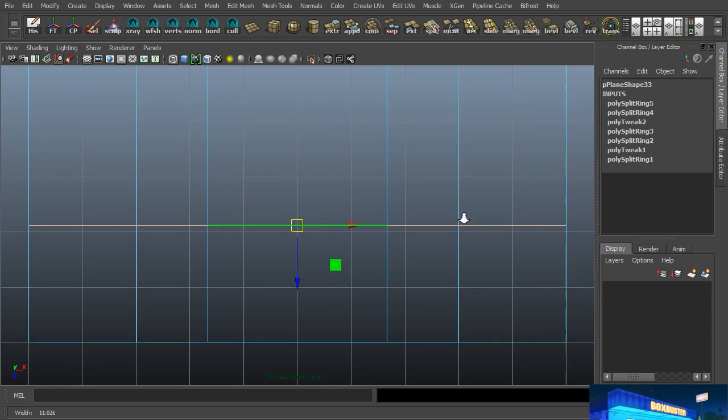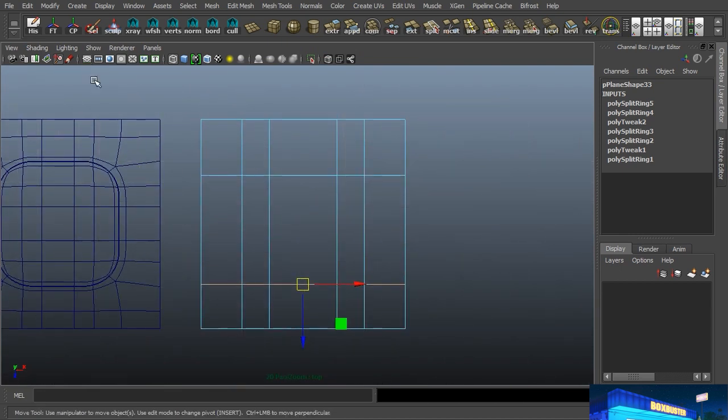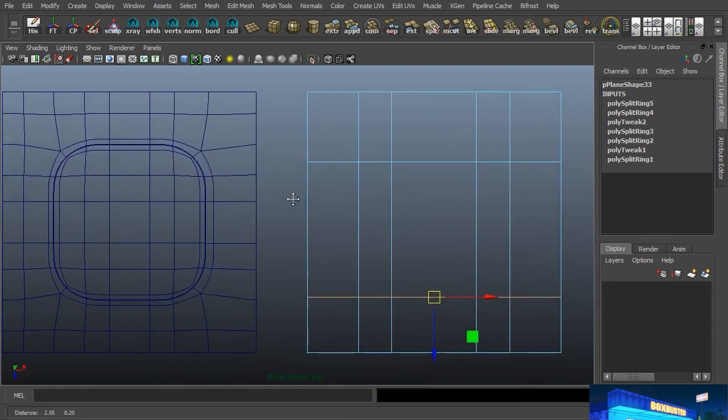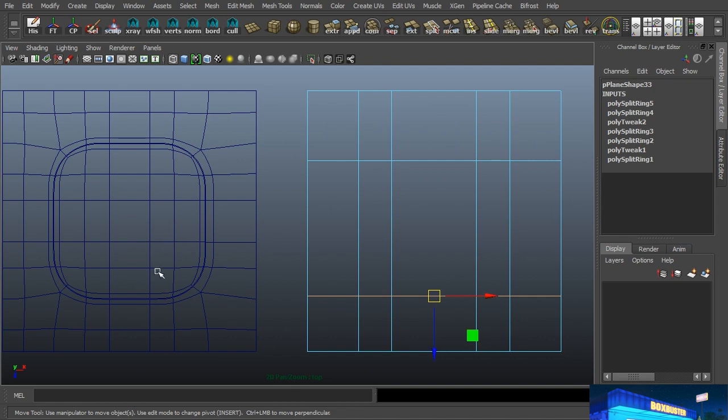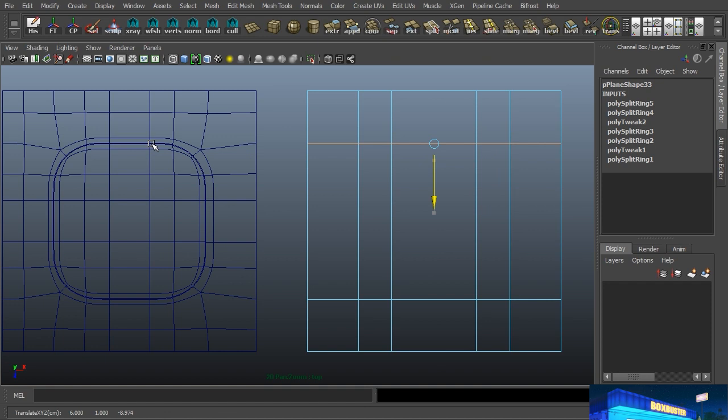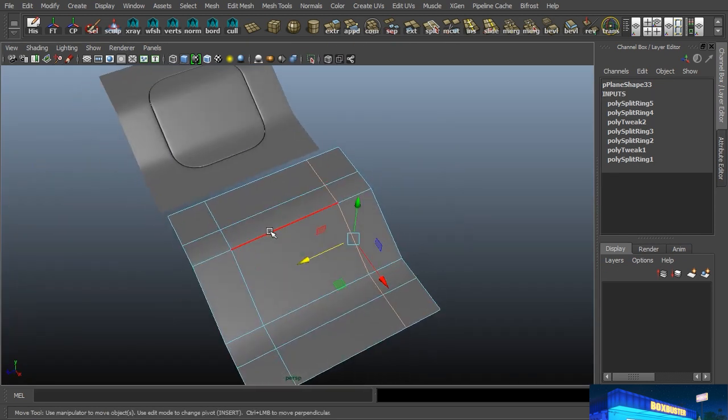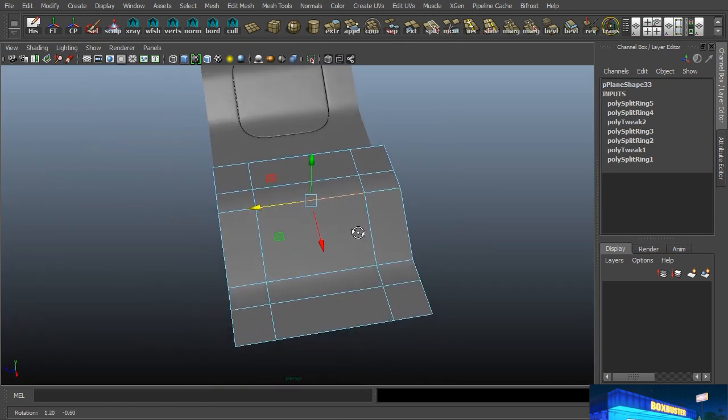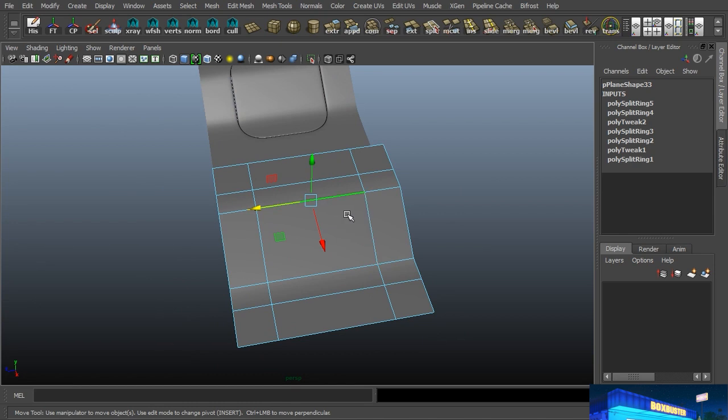So let's jump into our top view. We'll turn off the grid so we can see. And we have reference here that we can use if we wish to. So I can get this moving in that direction, and then I can snap to that center line. And same thing on this one, I'll snap to that center line. So that gives us that edge that's running through there that we can use. All right, we're definitely going to need a center line on this. So maybe this one, we'll just Ctrl right click, and we'll go to there, and that'll center it perfectly.